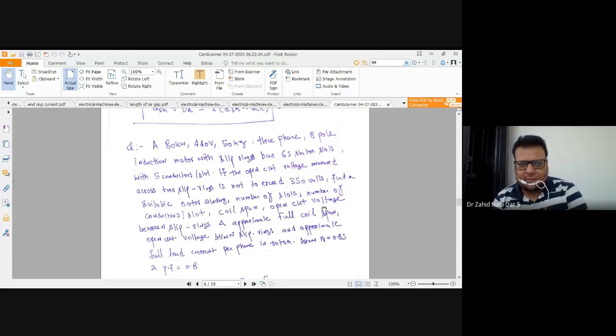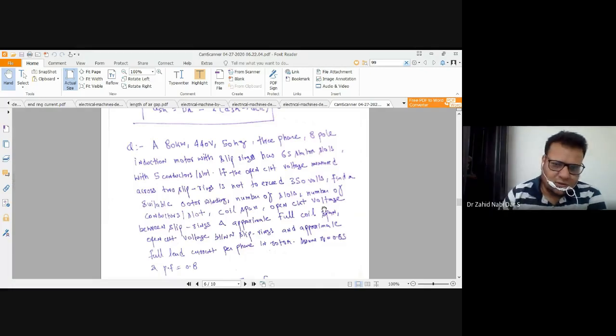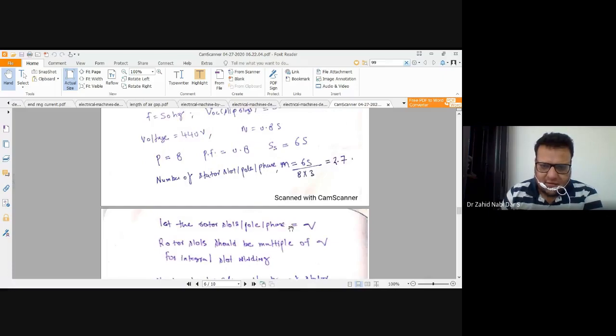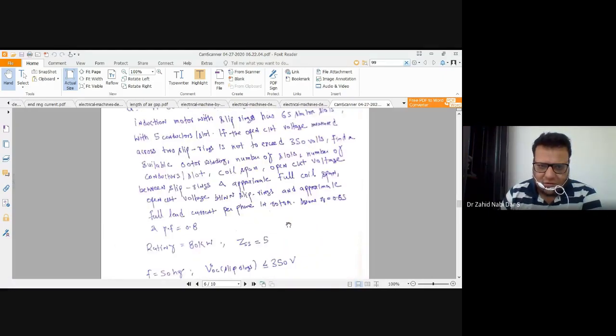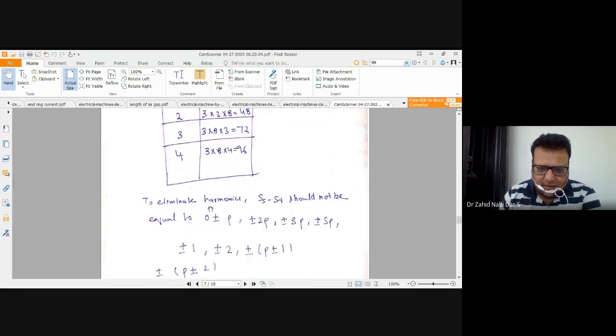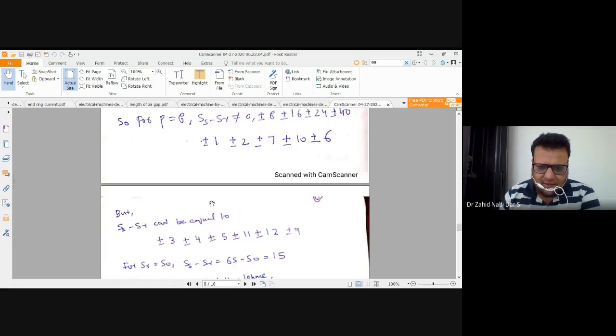So it is better, because the starting torque in an induction motor is 200% times the running torque. So for a smooth operation of an induction motor, it is better to run it in star connection. If it is not mentioned and it is a wound rotor induction machine, you can always take it in star, and now you can get these values.